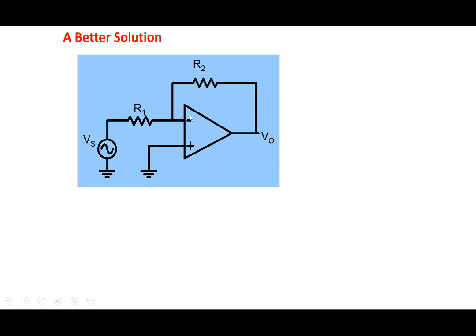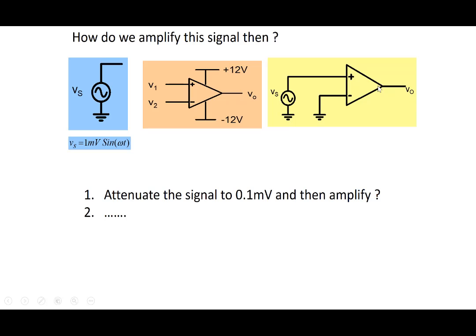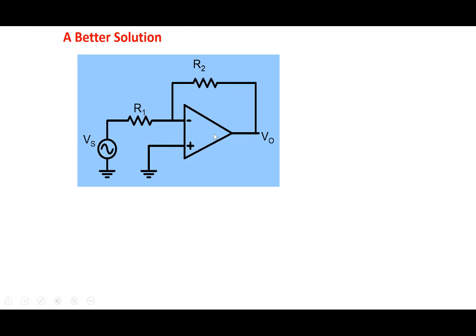We make a circuit of this particular kind here, right? So there's an R1 and there's an R2. So that's what we said. We wanted an amplifier, but we could not directly connect the input and make an amplifier like this. But now we can take an op-amp, add two elements here, R2 and R1, and now this whole thing acts like an amplifier. Okay, so we have customized this particular one as an amplifier. Now you connect the source here and you take the output here. And we will show you that V0 by Vs is simply equal to minus R2 by R1.